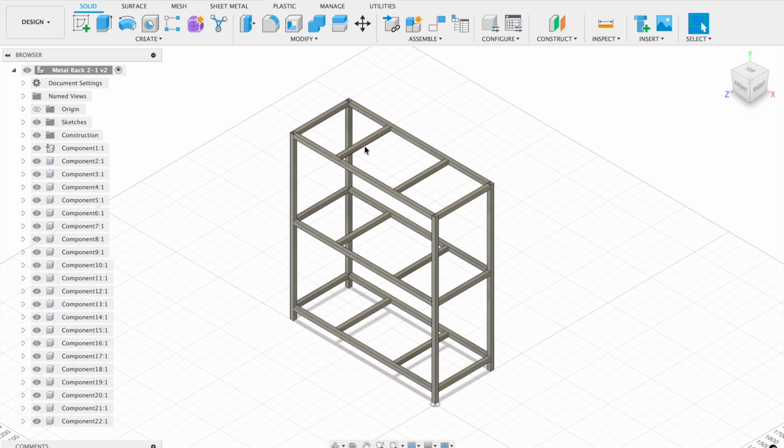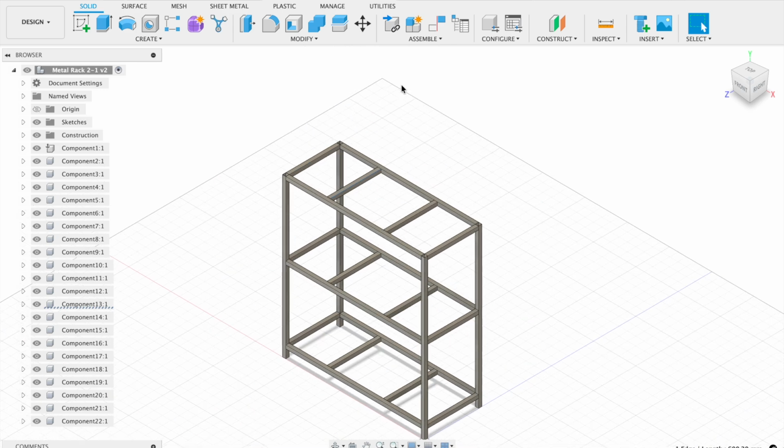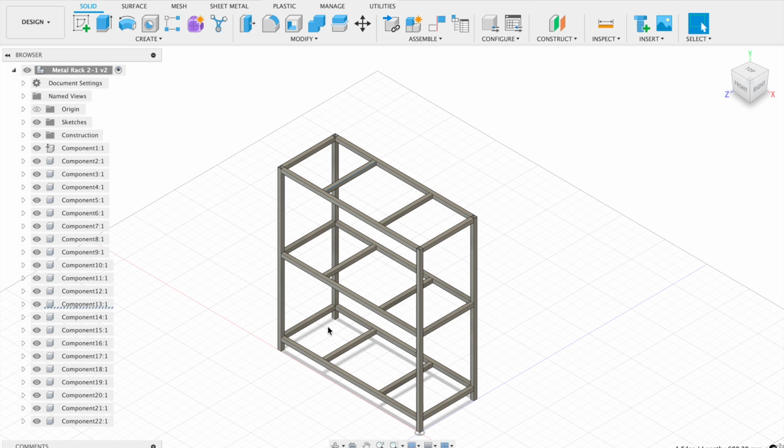In fact, you can kind of see this here. If I zoom in and I just look at the length of this line, you can see that it is 600.2 millimeters. So that means that there is a 0.1 millimeter overlap on the right side and on the left side. What I'm going to need to do is join all these together.